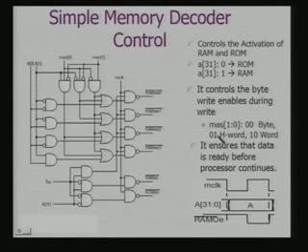Now, the other interesting thing is that this one, what we have got is this mask: 00 is byte, 01 is half word, 10 is word. Now, these signals are being fed here, and the logic is with regard to the different RAM write signals.